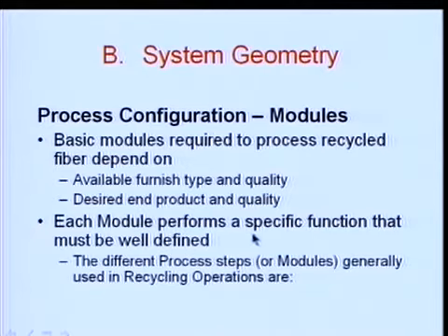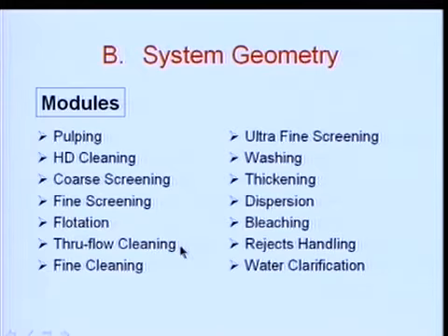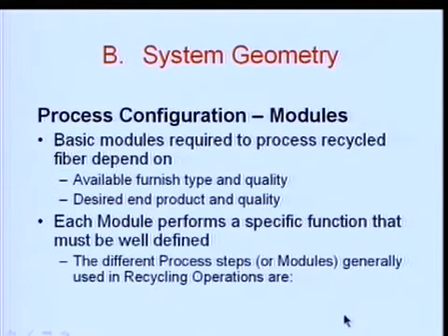So each module performs a specific function that must be well defined. What are these modules? Here are the modules: basic pulping, high density cleaning, coarse screening, fine screening, flotation cleaning, then again screening, very ultrafine, washing, thickening, dispersion, bleaching, rejects handling, and water clarification. These are the basic modules that you have already studied and gone through.